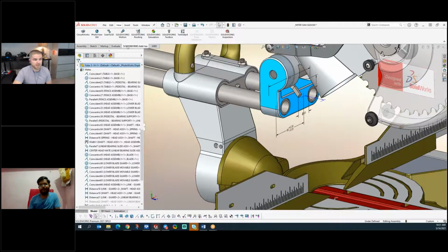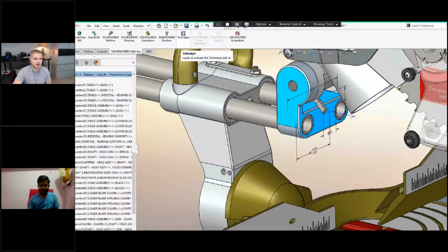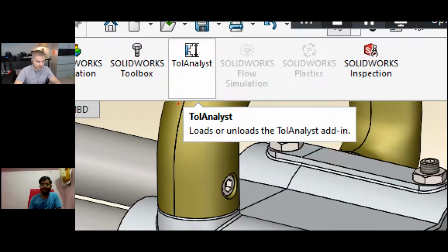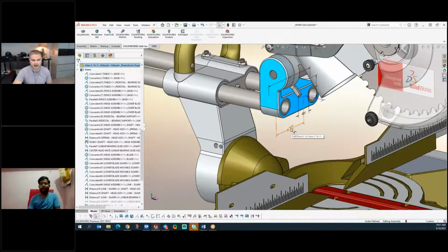There is a tool in SolidWorks called TolAnalyst, and TolAnalyst allows you to do tolerance stack up analysis. So when you input all this information, this part has this tolerance and this part has this tolerance, and you stack all that up, this tool can actually analyze how far out the model could possibly be, worst case scenario, if everything was on the far end of the tolerance spectrum. That tool can do that. But really, when I'm adding that, it's not changing the model at all.